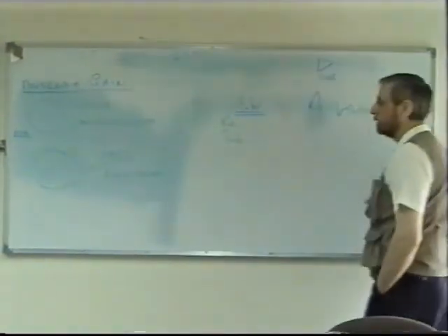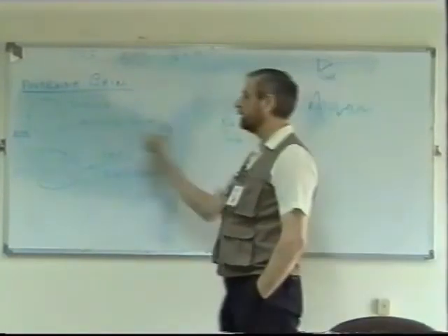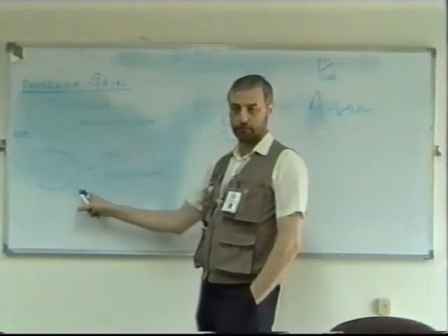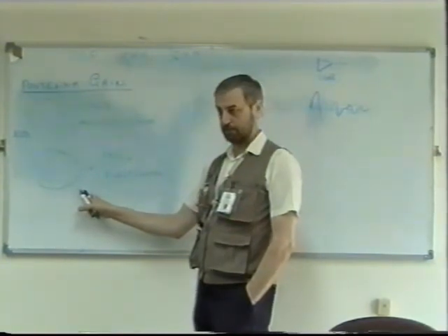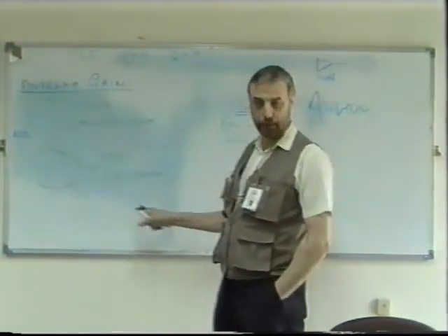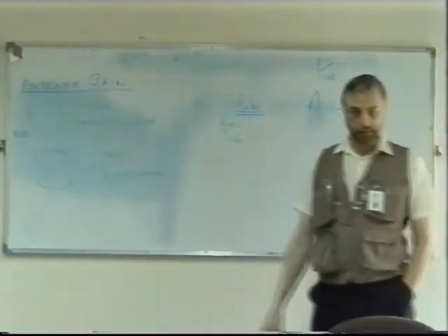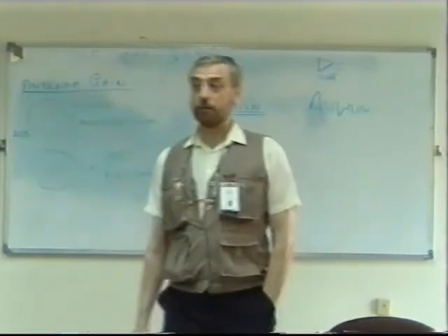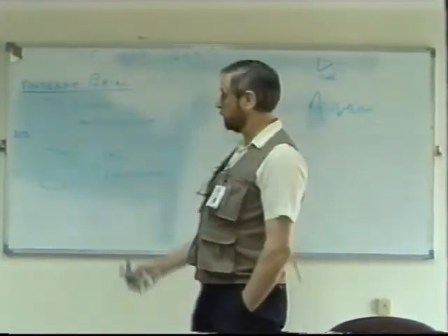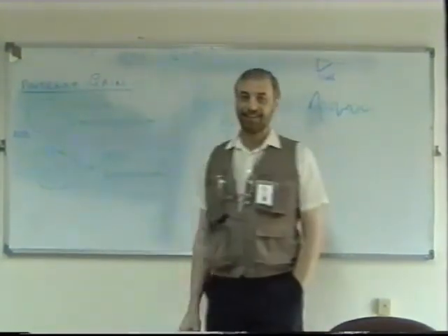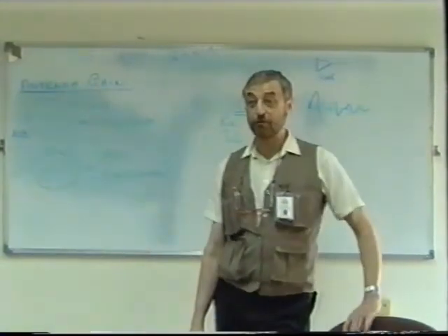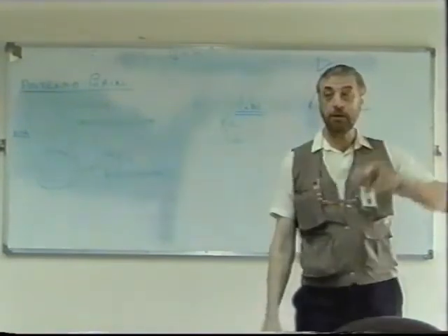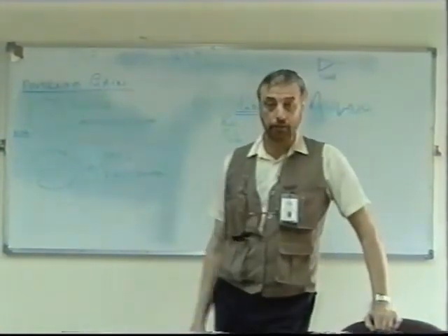Now what I want to do now is consider the same situation, only using a directional antenna, a Yagi, for point to point. Yes, of course, with a Yagi, because it's directional, we're basically talking about point to point, aren't we? We wouldn't use this sort of antenna for mobile, for obvious reasons, because as the car goes around, or whatever it is we want to communicate with, it could be behind the antenna, and we're not going to get as much gain.